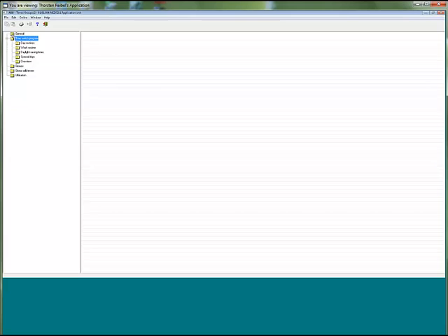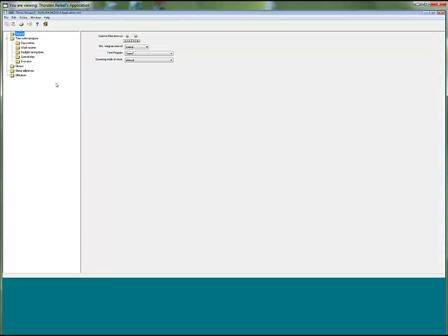First of all, some general functions available here. In principle, I don't go into all details, but allow me to show you this a bit here. If you activate a group with a lot of telegrams behind, or you have a time function, at the same time, a lot of functions should take place. You have maybe a lot of traffic on the bus. You can delay artificially here with this function, or with this parameter. You can say between each telegram, I would like to have a 300 millisecond delay. It's possible, yeah, if you want.